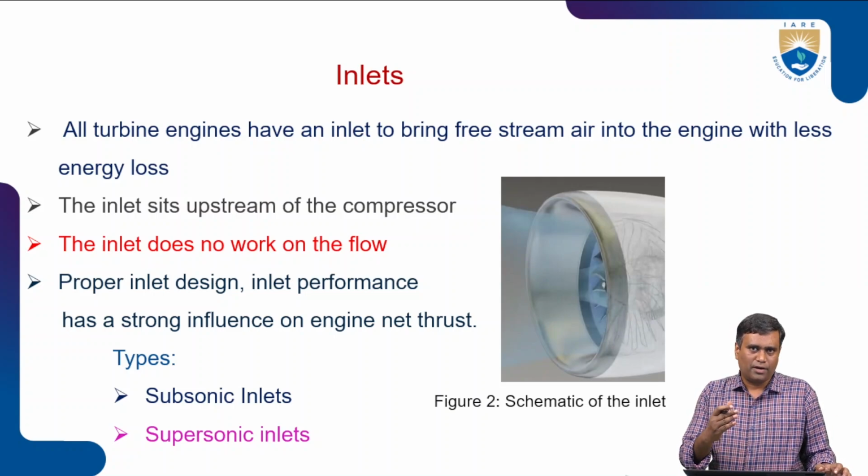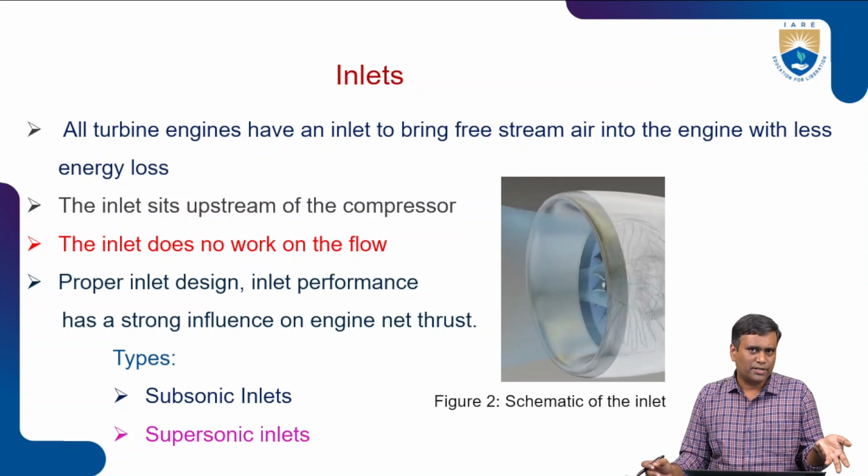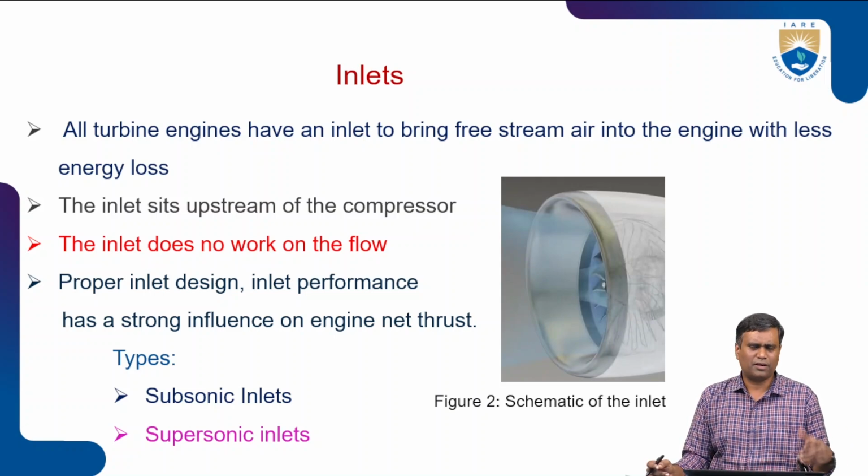The pressure losses, velocity losses and increased drag will all disturb the flow in the compressor, which will sometimes result in compressor stall or surge, and otherwise will result in unstable combustion, which is combustion instabilities, which altogether results in vibration as well as may lead to engine failure. So this is the importance of the design as well as selection of the right inlet.